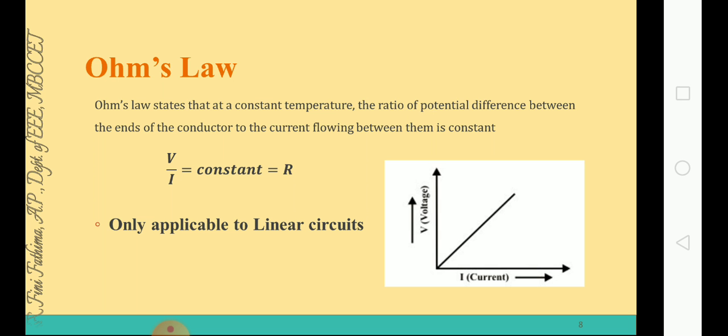Not only the resistance, the same applies to the inductor and the capacitor. In the last class, we discussed inductors and capacitors, isn't it? We derived the formulas for voltage and current. From those derivations, we know that in the resistor as well as the inductor and capacitor, the ratio between the voltage and current is always a constant. So we can say the resistance, inductance and capacitance follow Ohm's law if they are linear. If they follow Ohm's law, then that element is a linear element.